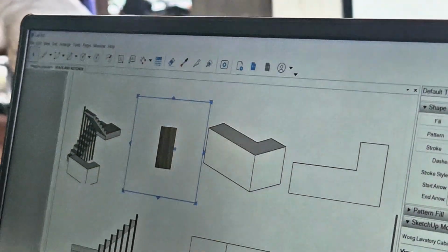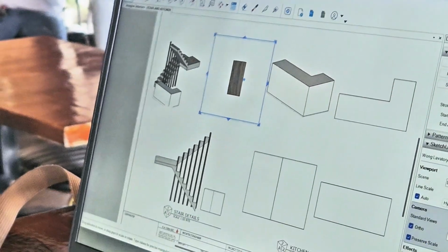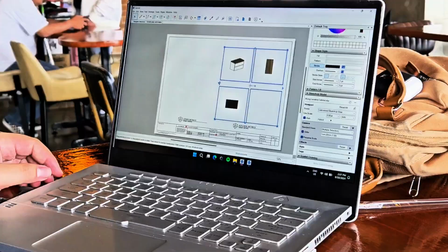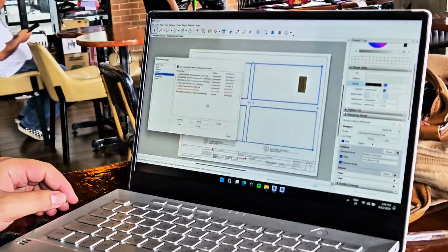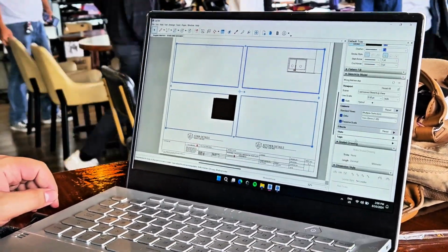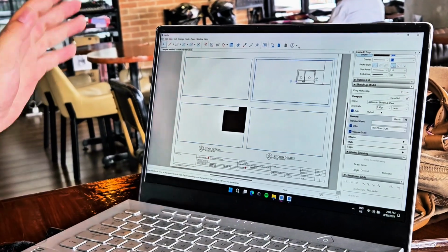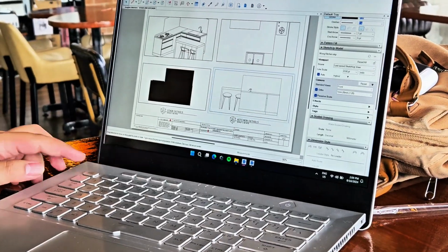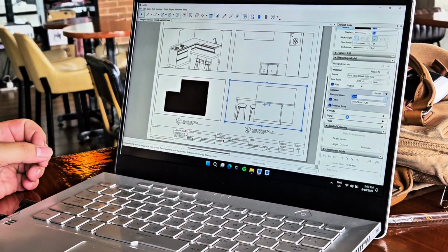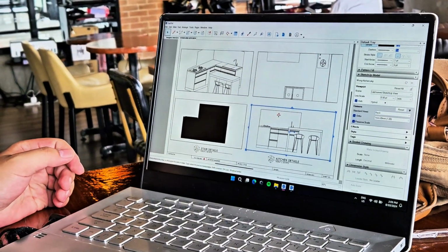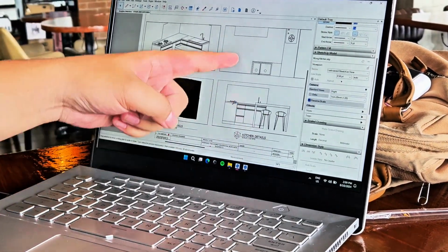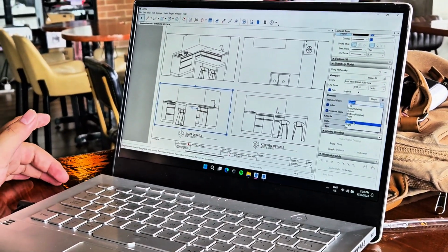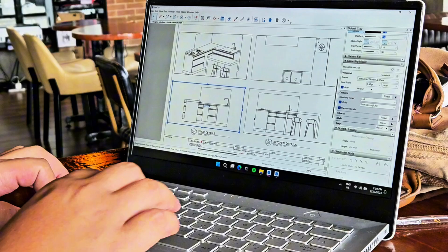If I change everything to one model, what do you think will happen? The same views. Let's do that. File, document setup, and click the SketchUp model to relink to kitchen. Make sure that these viewports are updated according to the view that you like. Isometry, top view, left and right. In this case, I have a view here that is the front view for my kitchen and not necessarily the model's front view. The viewport to my left has a different style, so I pick style and just match the properties. Then I update the view in standard views if I don't have scenes.